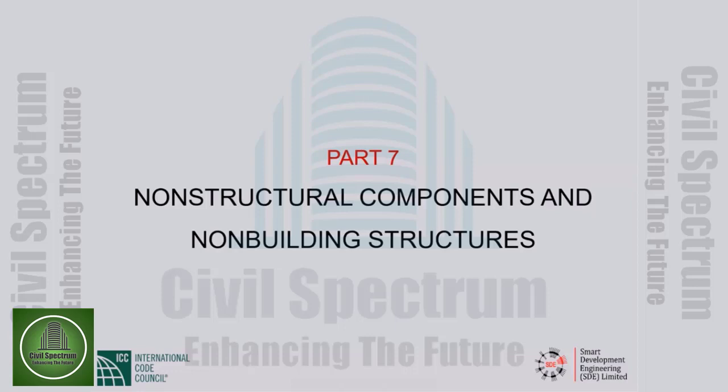The word spectral, very briefly: spectral displacement is the same as maximum displacement of a structure, specifically a single degree of freedom system, which means only one component of motion of one mass is possible. You see, it gets intricate in a hurry.